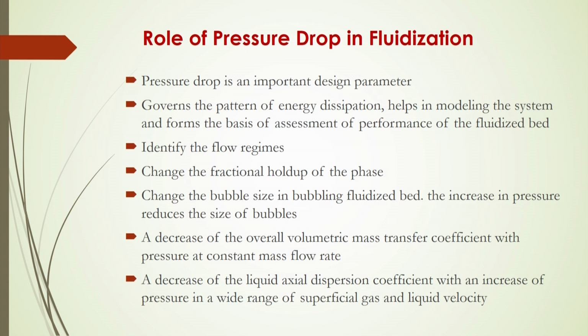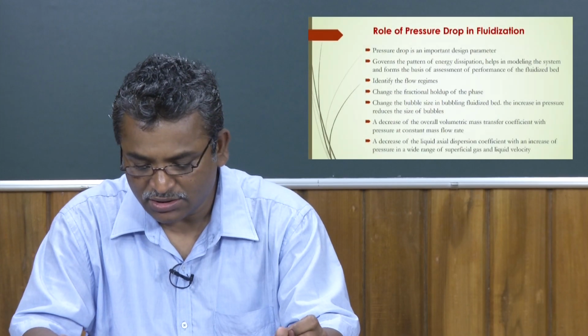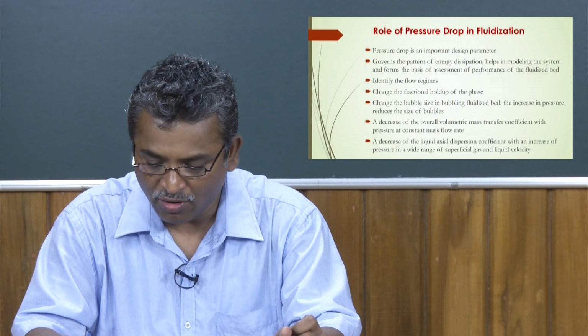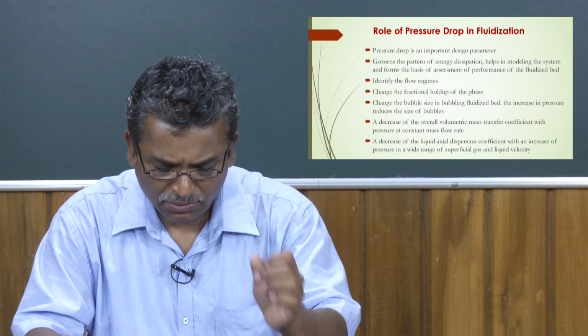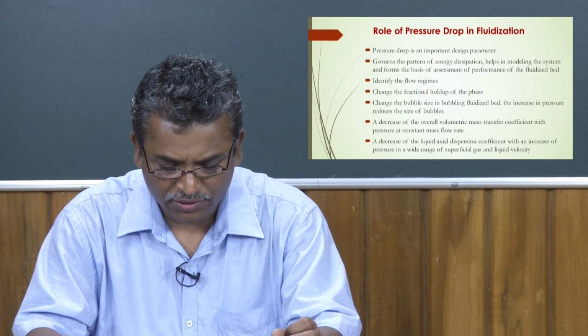It also changes the bubble size in a bubbling fluidized bed. Of course, the pressure drop has an important role in the size of the bubbles that are formed in the bubbling fluidized bed. In this case, if bed pressure drop is increased, the bubble size reduces.